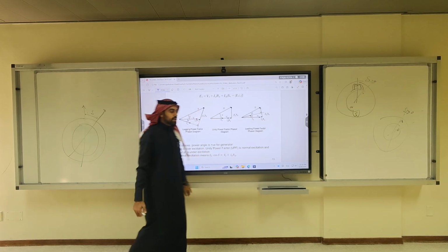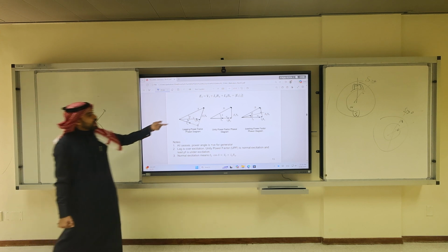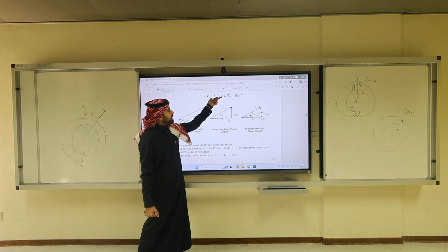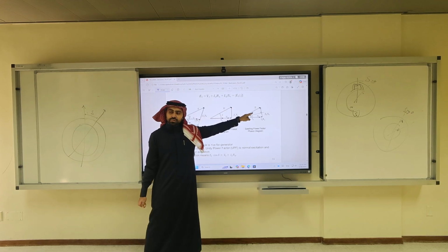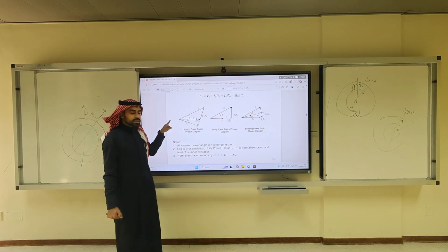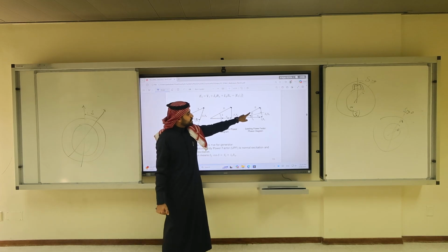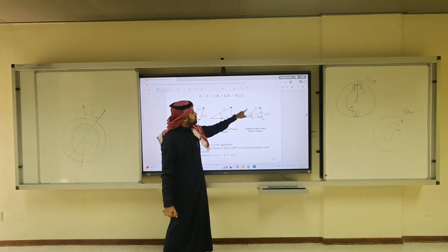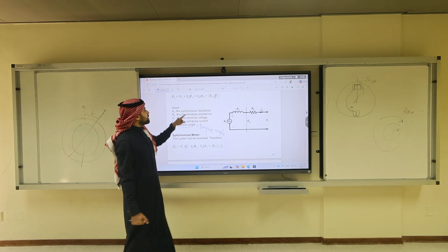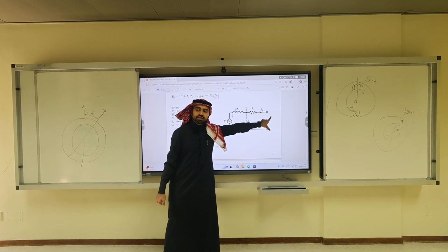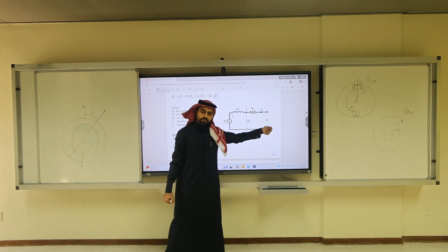The second thing I need to know is I need to apply this equation for a synchronous generator to calculate EF. Here we put it E. In all of the three cases, delta is positive, where delta is the angle between EA and the reference. What is my reference here? My reference is VT, because it's at an angle 0. So I'm measuring how much EA is deviating from VT.